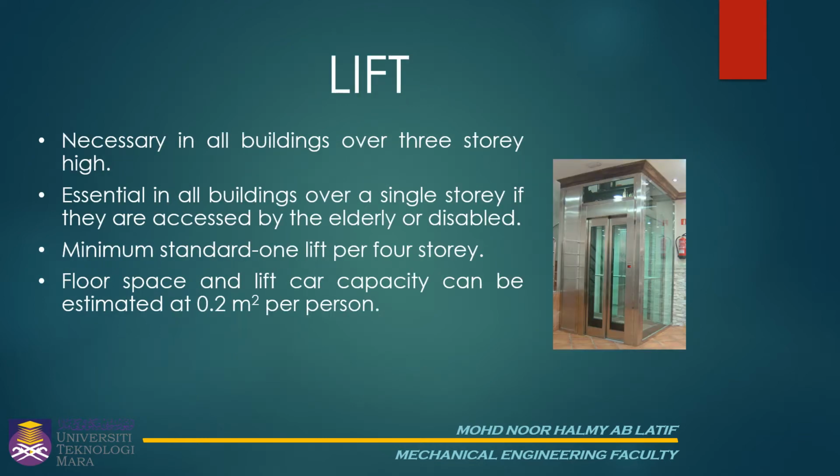Lift is necessary in all buildings over 3 stories high. It is essential in all buildings over a single story if they are accessed by the elderly or disabled. Minimum standard is one lift per 4 stories. Floor space and lift car capacity can be estimated at 0.2 square meters per person.